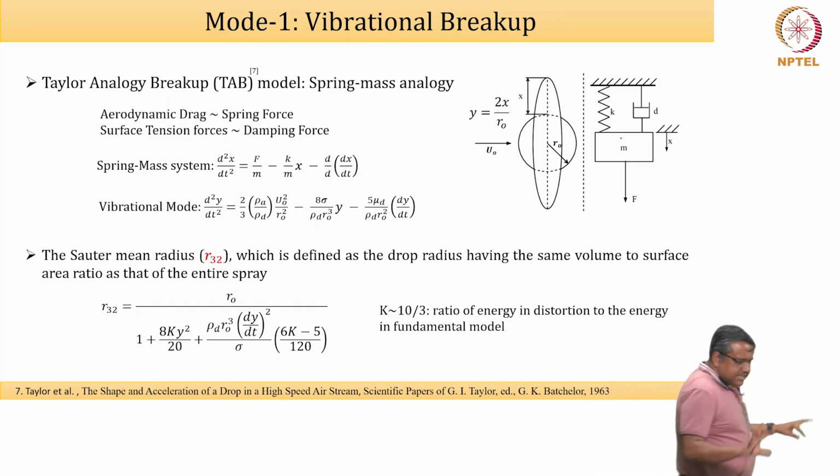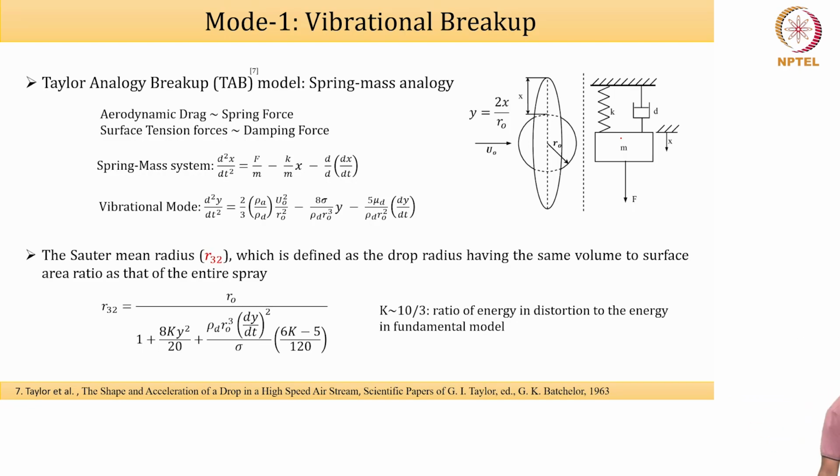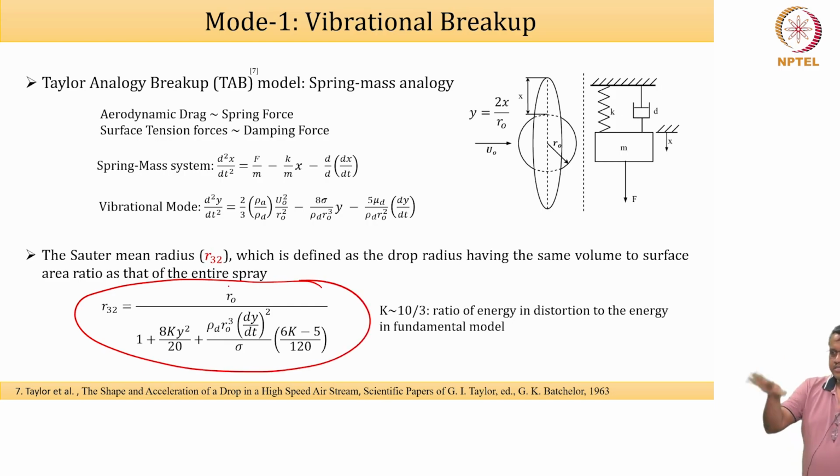So it is like a dashpot type of system, and these are relationships that you can produce by doing just an energy balance of the whole thing, daughter versus the mother droplets, and this is what you get. Typically, these modes of breakup are available at Weber number less than about 4. Weber number greater than 1 means you have just enough inertia to push things out of bounds, and 4 means that you are relatively in the lower aerodynamic or inertial range.